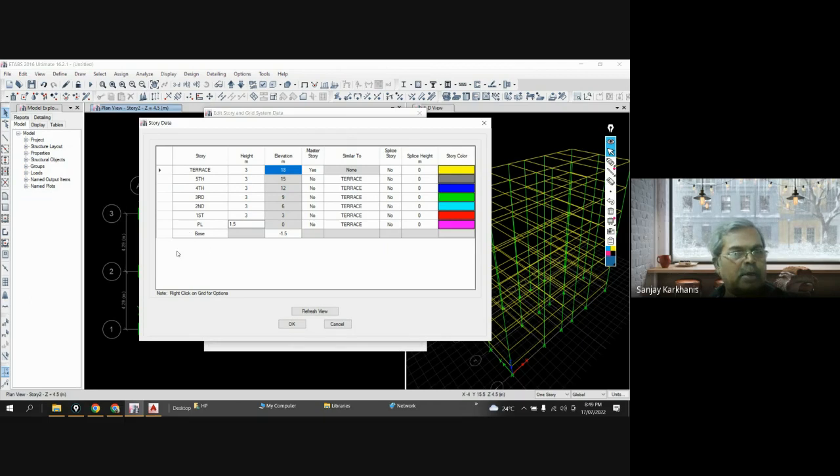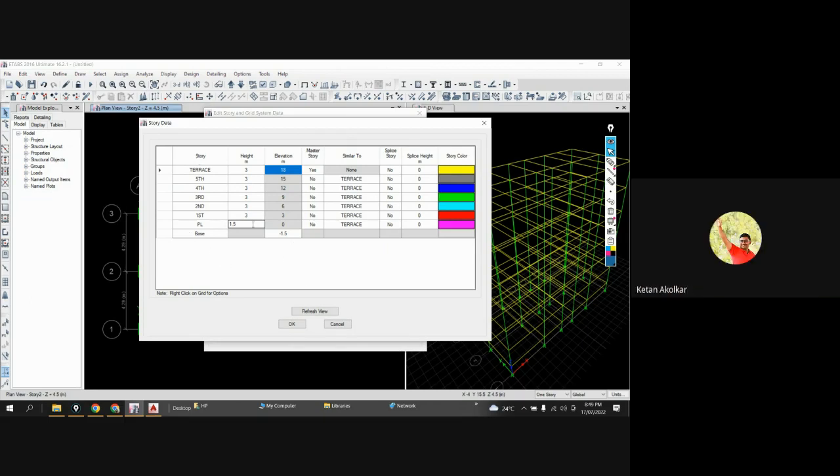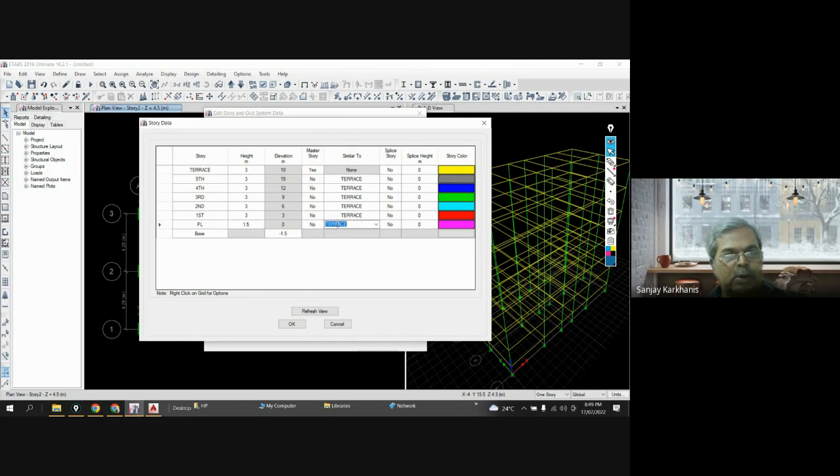Yes, sir. Did you understand this much? Yes, sir. Now I will say that plinth is similar to none. Okay, plinth is different. Now this first story is my master story, so I will make it master story. Okay, then this also I will make none. So, and now I will say this story similar to first. This story also similar to first. Clear?